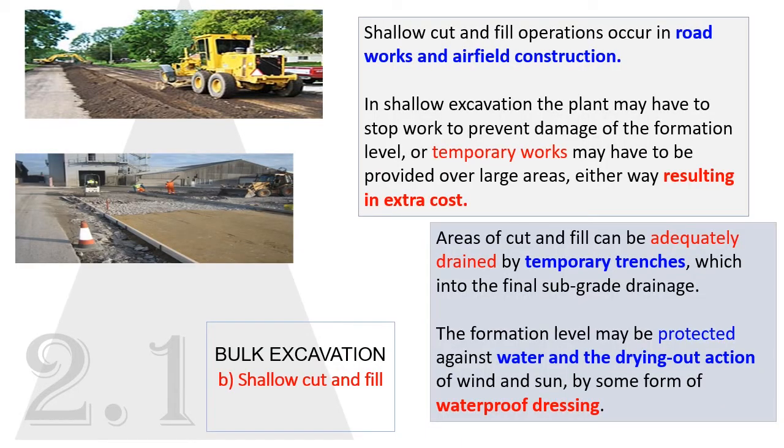Another bulk excavation operation, shallow cut and fill operation, occurs in roadworks and airfield construction. Areas of cut and fill can be adequately drained by temporary trenches, from which the water will be drained into the final subgrade drainage. The formation level must be protected against water and the drying out action of wind and sun by some form of waterproof material.